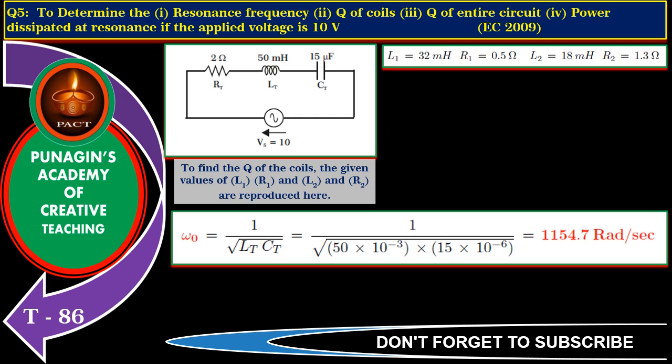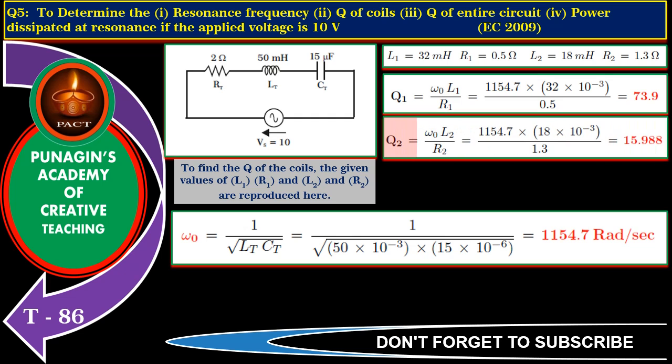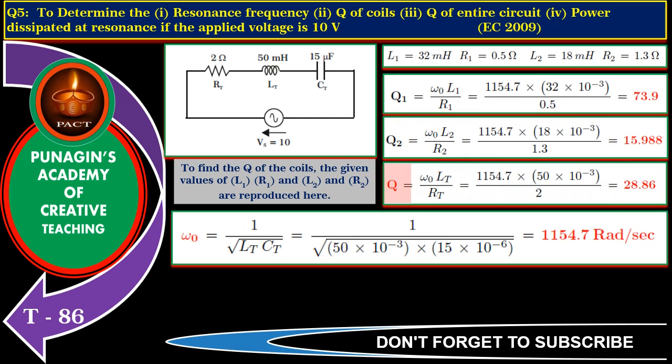To find the Q of the coils, the given values of L1, R1, L2, R2 are reproduced here. We know Q1 is equal to omega naught L1 divided by R1. By substituting the values and solving, we get Q1 is equal to 73.9. Similarly, Q2 is equal to omega naught into L2 divided by R2. By substituting the values and solving, we get Q2 is equal to 15.988.